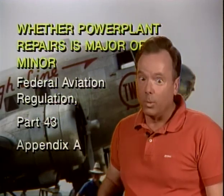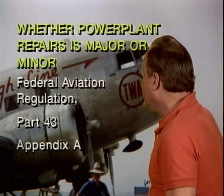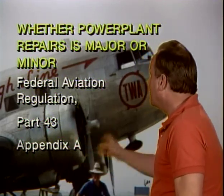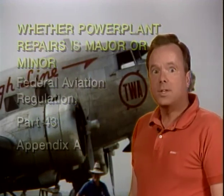All right, what is the publication to use to determine whether a powerplant repair is major or minor? Well, once again, would you guess you go to the Federal Aviation Regulations? Well, if you guessed that, you're right, because you'd go to Part 43. Appendix A tells you whether a repair is major or minor. Now, let's take a look at another one.